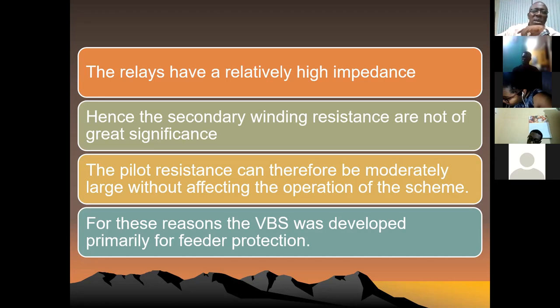So all the other equipment that we are talking about in terms of using differential, they are all located in a small area. So your bus bars are within the substation. And the only issue you will have in terms of difference in wiring is the position of the CTs because of where they are on the physical bus bar. Similar for your transformer. We are accustomed to transformers that we possibly can see the top of.